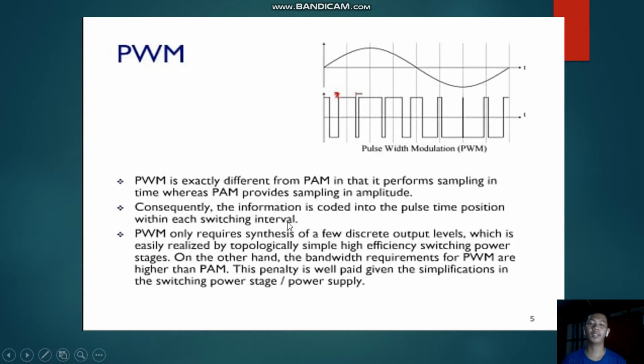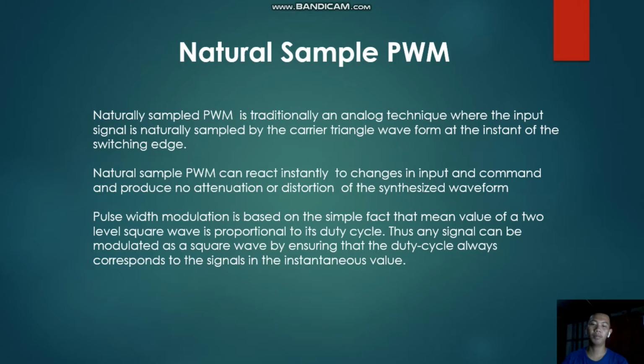PWM only requires synthesis of a few discrete output levels, which is easily realized by topologically simple, high-efficiency switching power stages. On the other hand, the bandwidth requirements for PWM are higher than PAM. This penalty is well paid given the simplifications in the switching power supply.